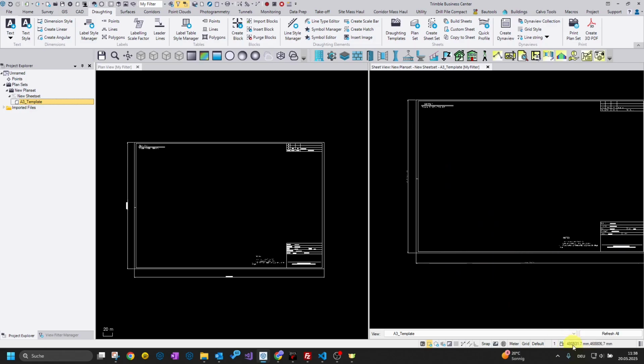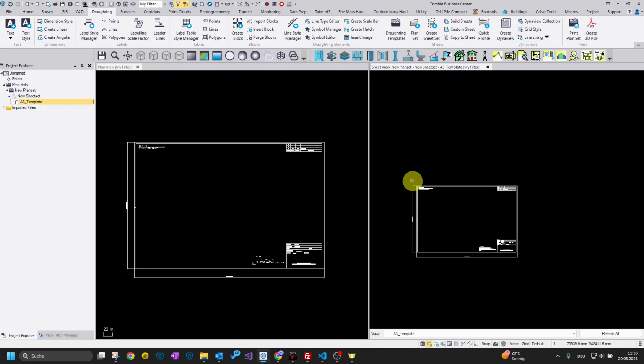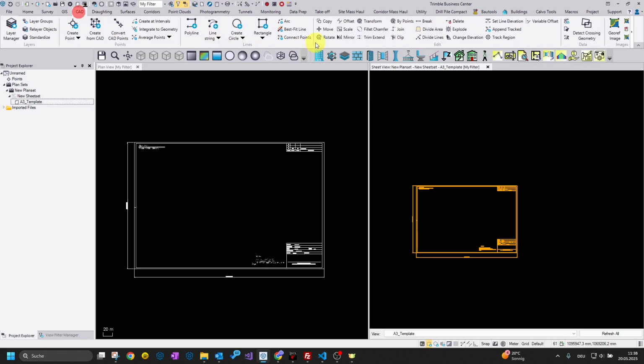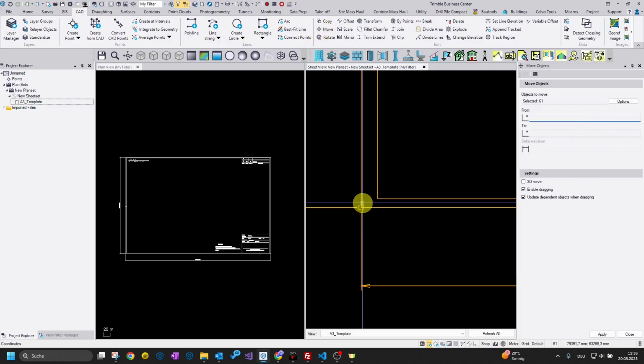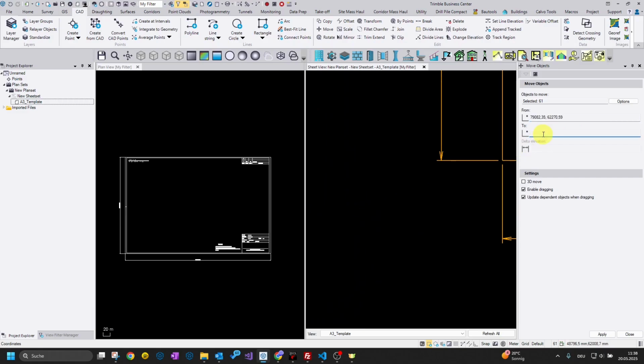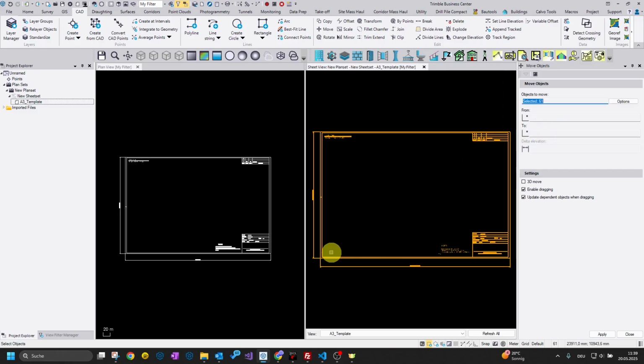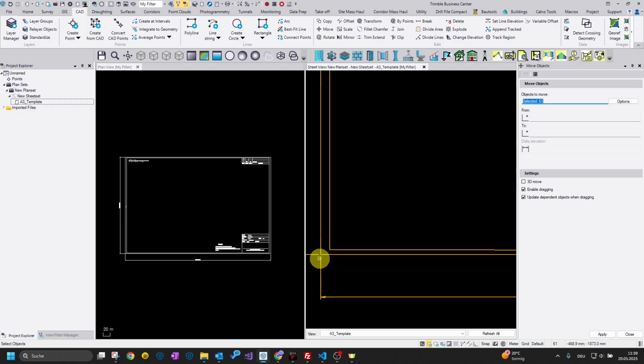So first, if you have a look at the coordinates, we see that the lower left coordinate is very far away, so we have to put everything on the 0, 0 first. So we have to move this corner to the 0, 0, 0, semicolon 0. So zoom extension. So we are now, if you have a look here, we are now here on the 0, 0.